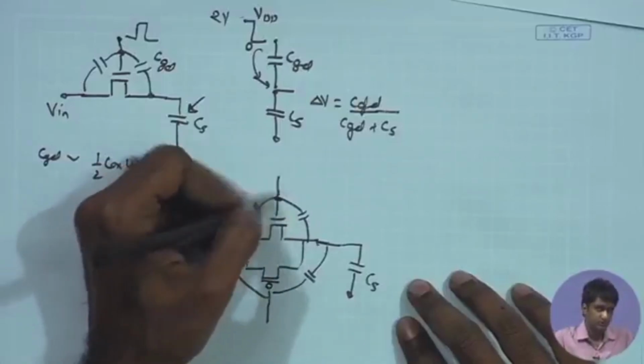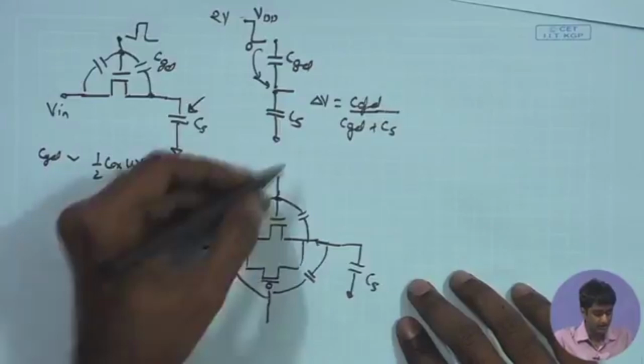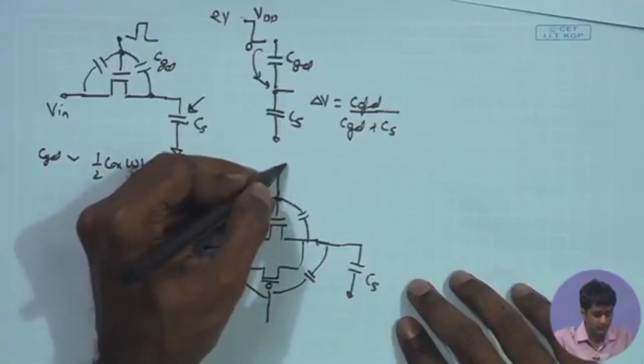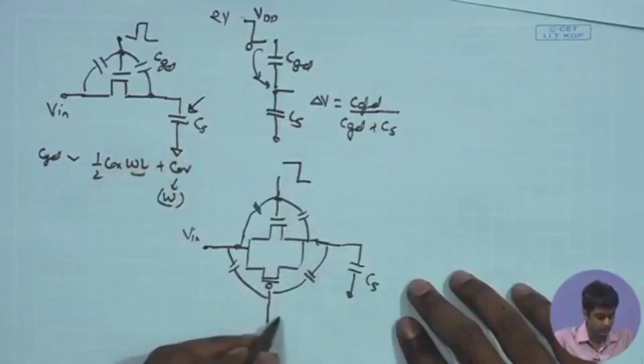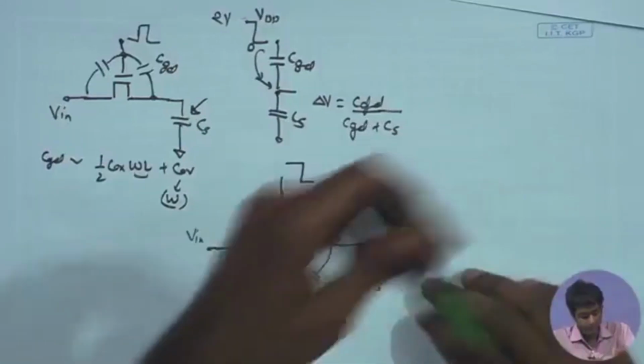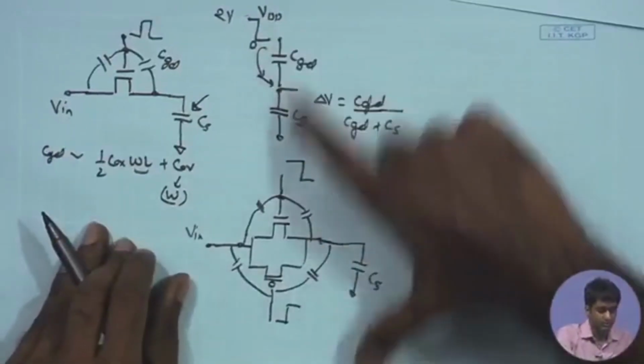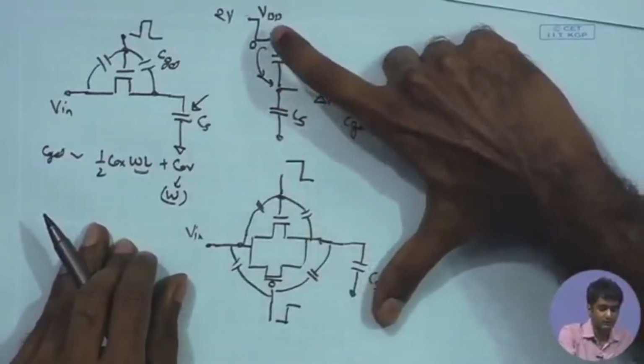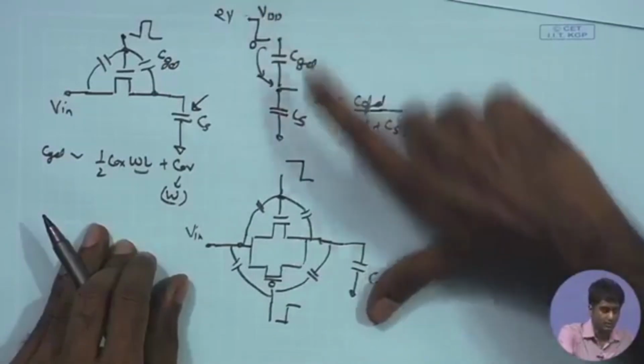And remember, if I talk about the clock action for turning off this MOSFET, the clock will be going in the negative direction, whereas for turning off the PMOS, it will be going in the opposite direction. So, the effect of clock feedthrough, if I assume this equation, is just opposite. On one terminal you have the signal going from 0 to VDD, on another one VDD to ground.